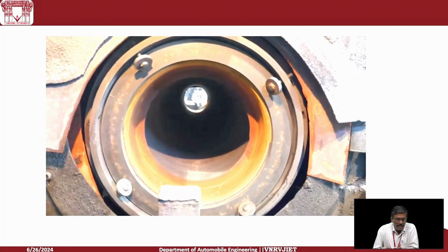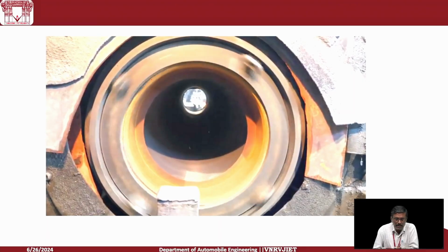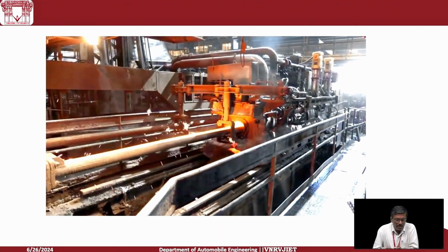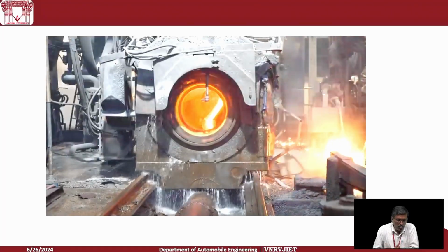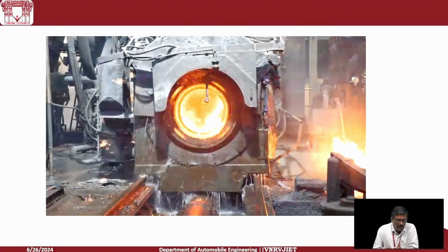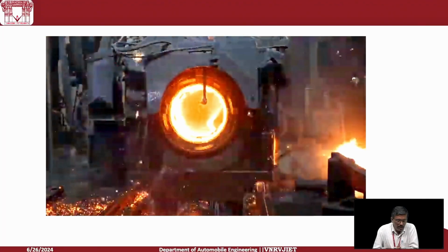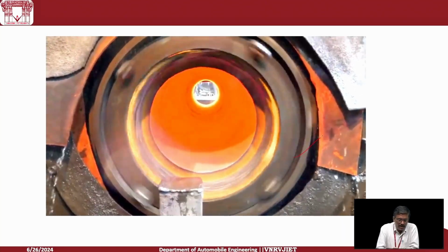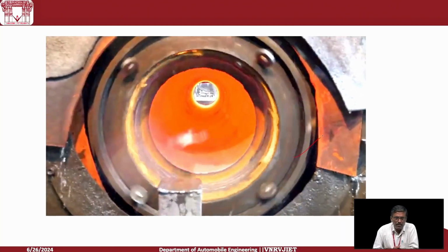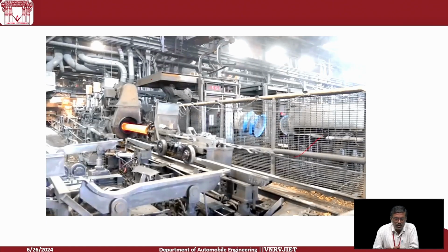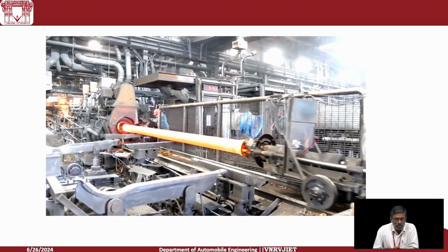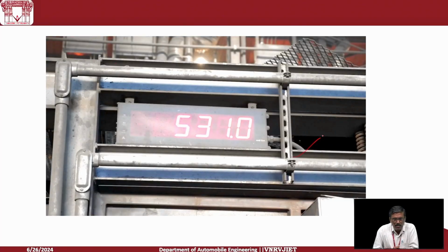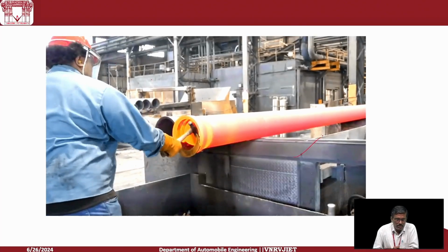Now the mold begins to spin as the casting machine travels uphill to receive the raw material in the form of liquid iron. The iron is poured into the mold at 2,500 degrees Fahrenheit. The casting machine moves slowly downhill as it pours the raw material, so that the mold is evenly filled with the molten iron. Here the mold is in the form of a hollow cylindrical shape. Now the pouring is over and solidification is almost over. Now you can see the hollow cylinder obtained from the centrifugal casting process.